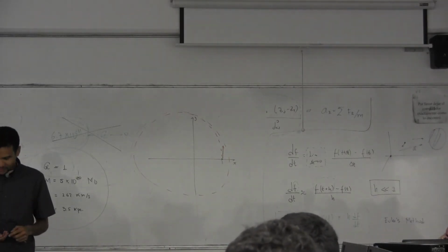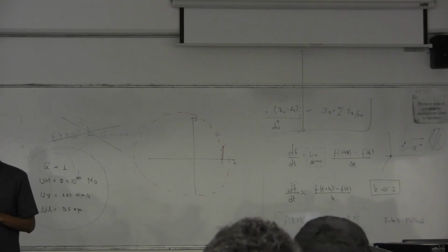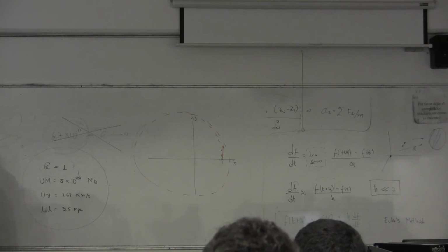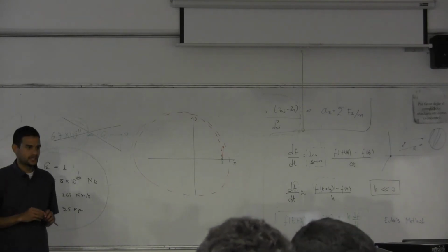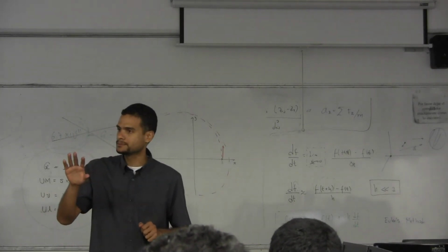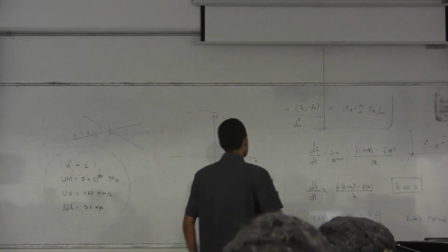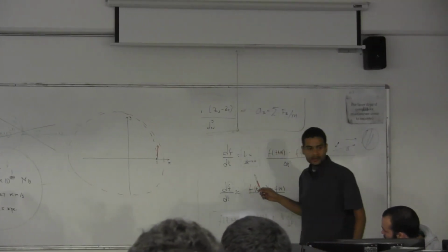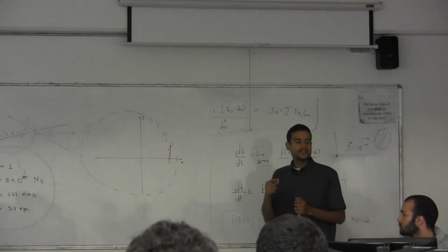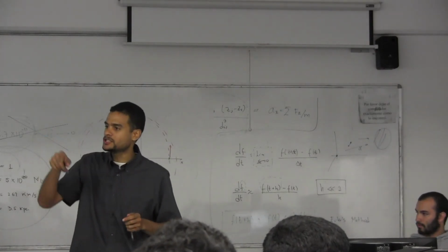And then the community comes on top of me and tells me, please, first, learn to run simulations. Because one actually needs to make what we call numerical convergence tests. A convergence test means that you take the parameters of your model, in this case the parameters of my numerical approach, which is the time step of integration, and you have to vary it until you find convergence.